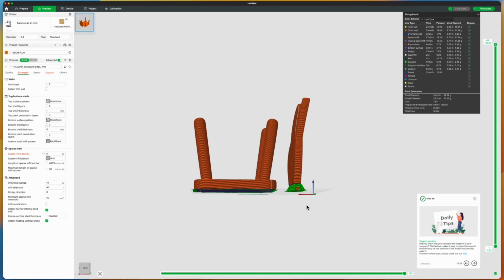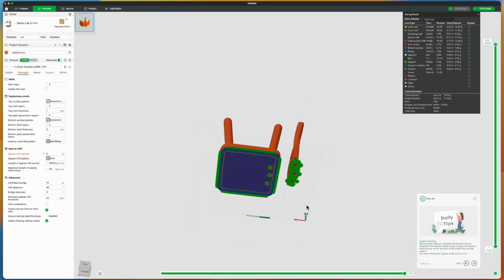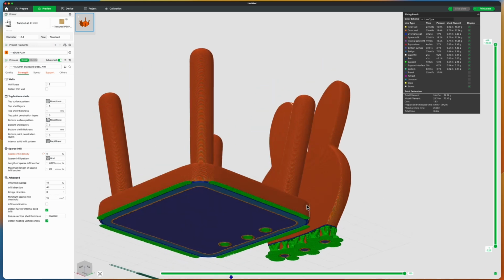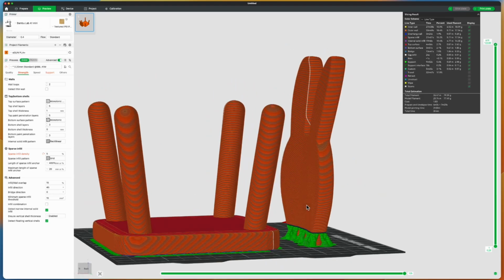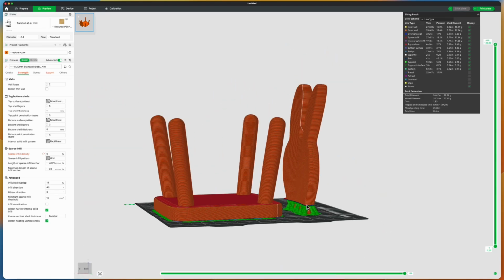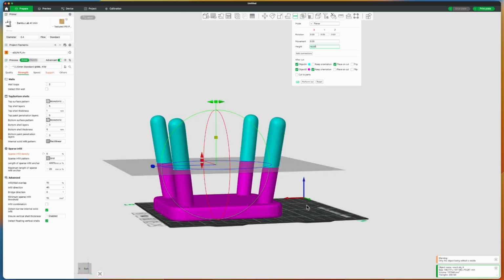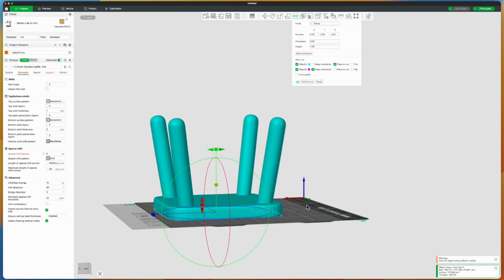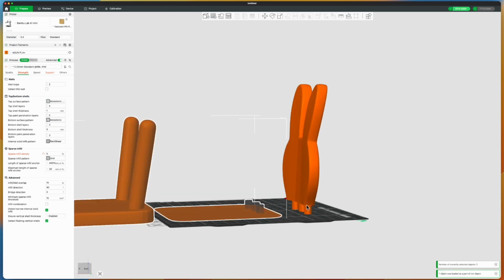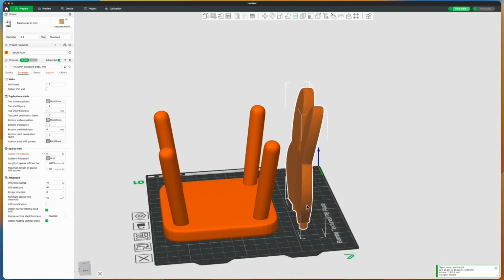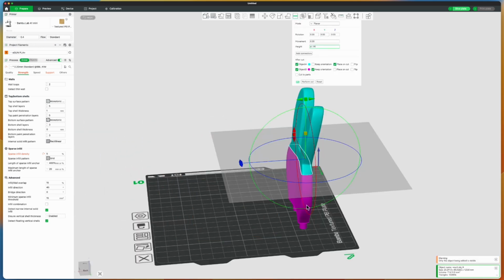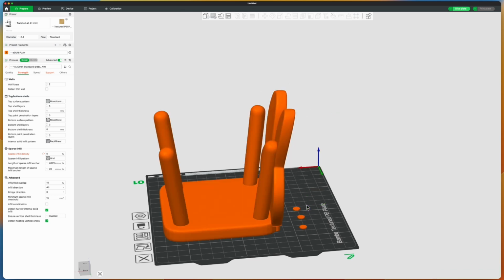Let's slice and... oops! We have another small issue. The seat has a slight depression that might cause printing problems. Let's make a quick 1 millimeter cut to flatten this surface. And then delete the cut portion. But now our connector heights don't match anymore. So we also need to cut 1 millimeter from the backrest plug to make sure everything lines up properly.